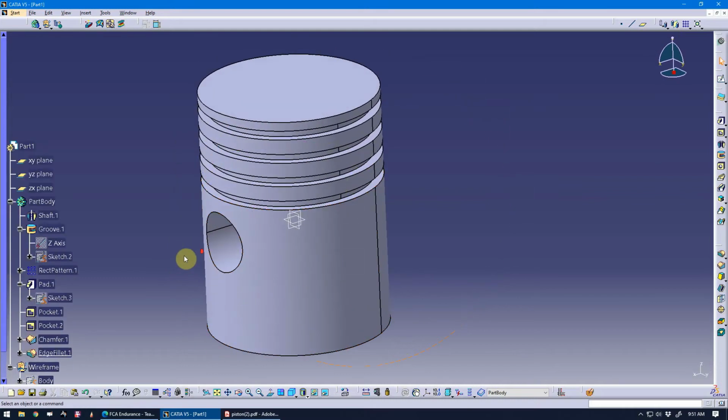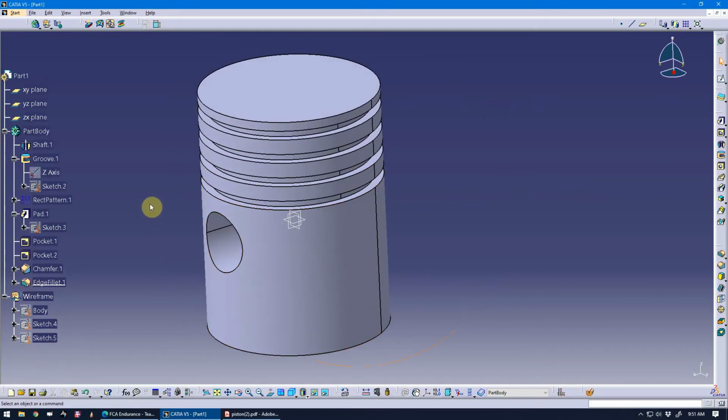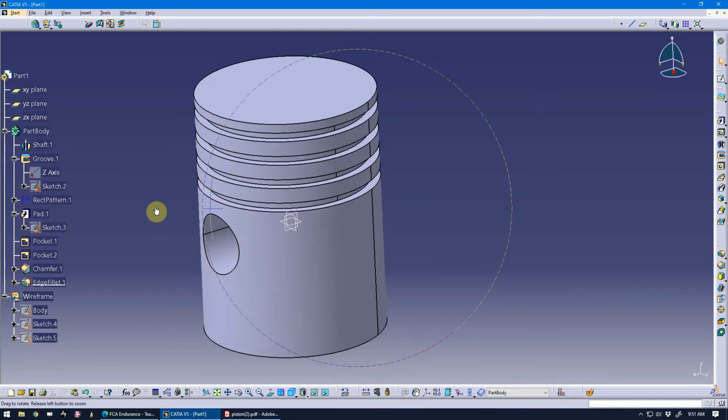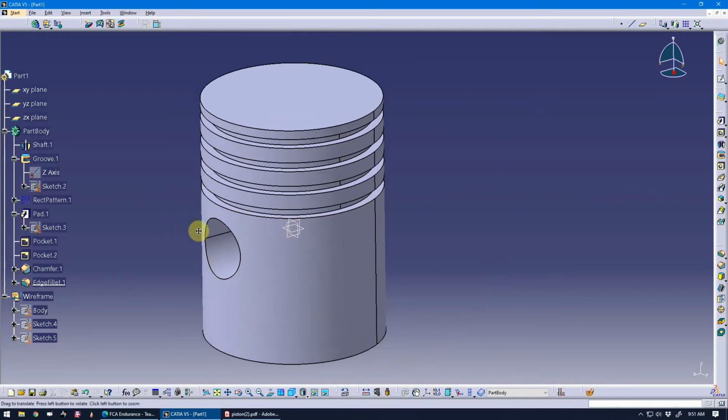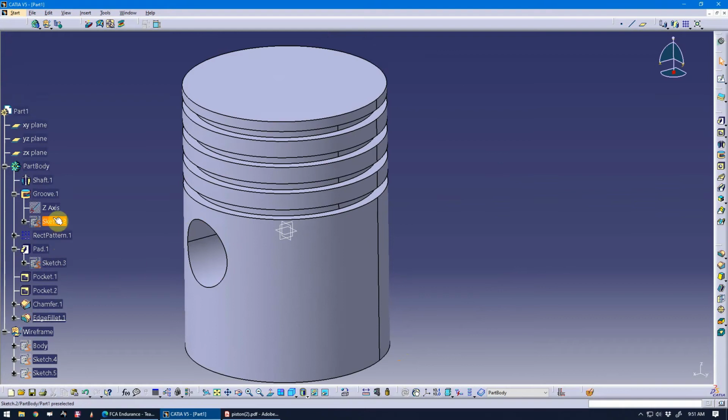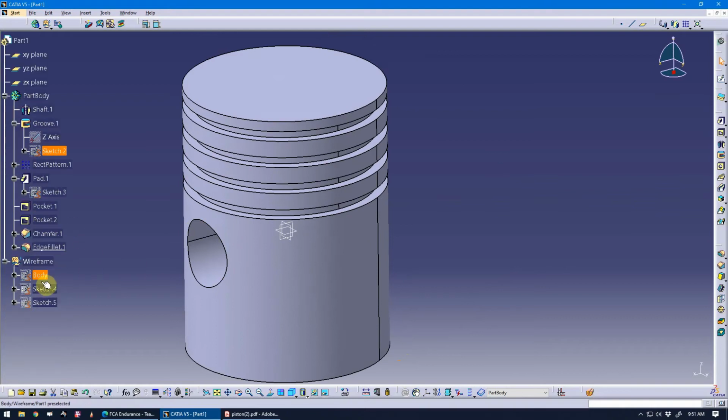So that's my way of doing it. I've seen students do it other ways, and I thought it was adequate. And I've done it other ways as well. A couple of things as I work through this. One is I forgot to put this sketch down here. Now, one way to work around that is to copy paste, because this is a body, right? So I can't just move it to a geometric set. But I can copy paste this one in and then redefine the sketch as that new copy. Sometimes that works, sometimes it doesn't. I'm not going to worry about it here.